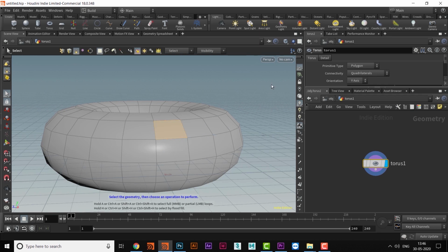If you drag, to select this area I have to contain the whole primitive within the box. If I take this area, or this area, it will not be selected until the whole primitive is within the box.